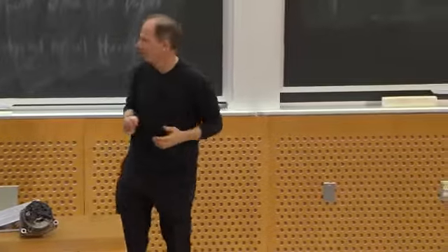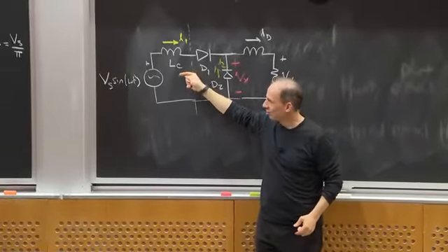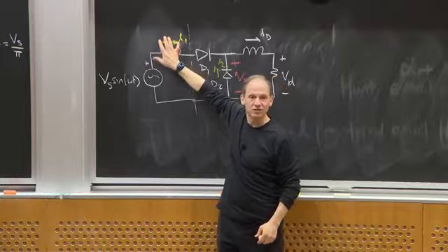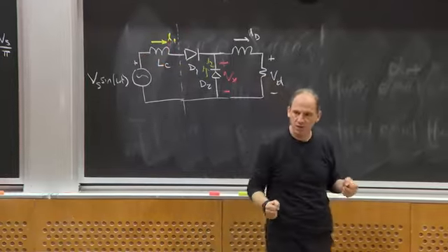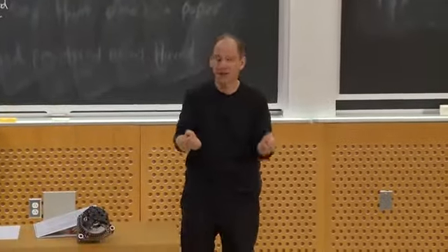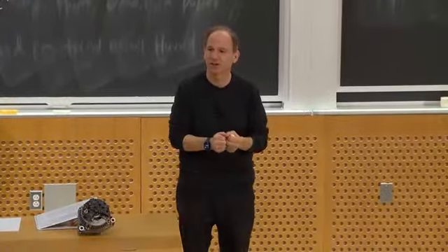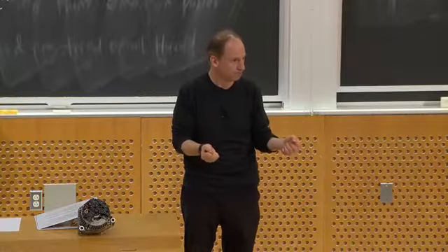So generally, you're not looking back into a perfect voltage source when you're looking into the wall. There's some source impedance, and that's typically inductive. Likewise, in the high-frequency converter I mentioned, it has a transformer in it, and that transformer has some parasitic inductance, and you're sort of stuck with that. And so you're stuck with what that does to you.